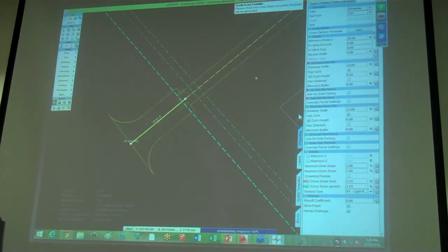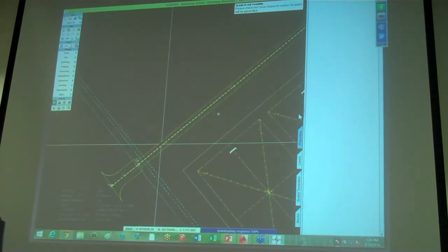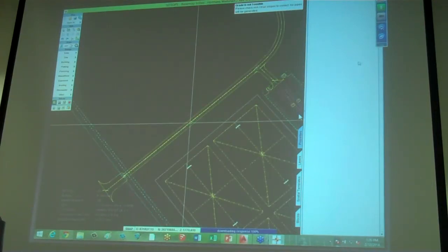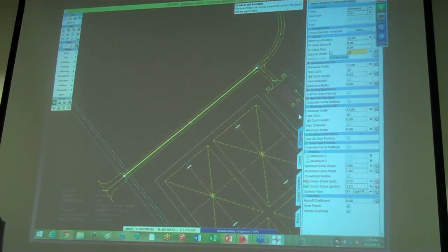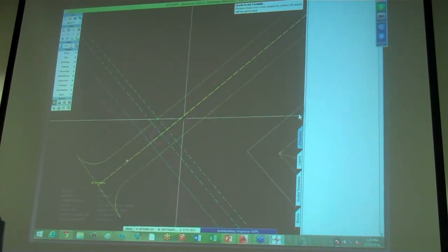And then back here, I'm going to tell this part of the roadway. Let's just go in, maybe not the whole thing. For now, let's just take this section. Say I want a 20-foot median. And if we zoom in, you're going to now see a median. We got the roadway. We got the different level controls and changes.